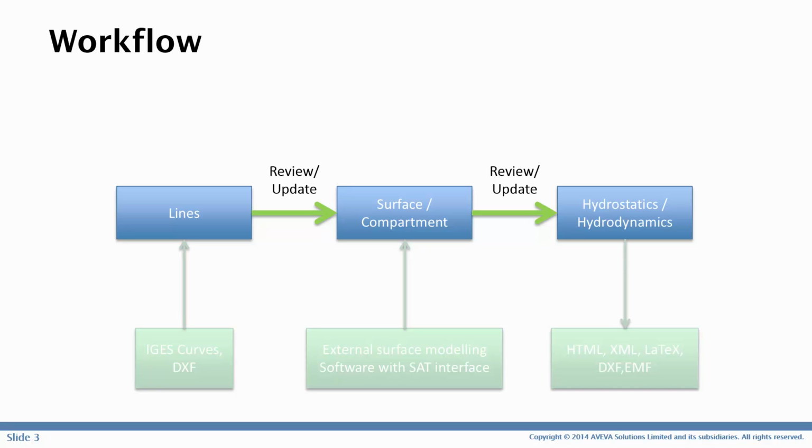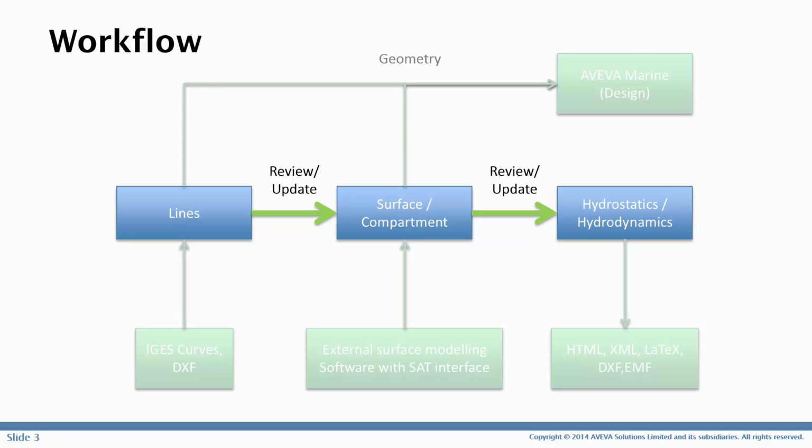The hydrostatics tools produce mainly reports. These can be exported in the form of HTML, XML or LaTeX formats, and then brought into Office tools like Word. Diagrams can also be exported as geometry using DXF or Windows metafiles. Both geometry tools can feed into the main AVEVA Marine Design databases. Hydrostatic results can also be posted into the AVEVA Marine databases and then custom reports generated using the reporting tool.